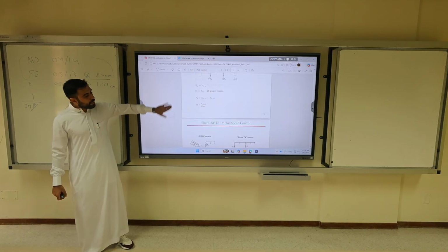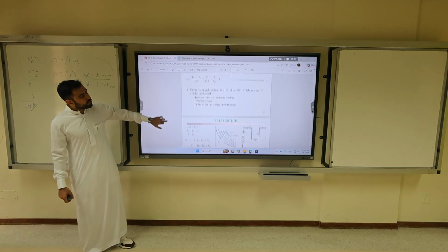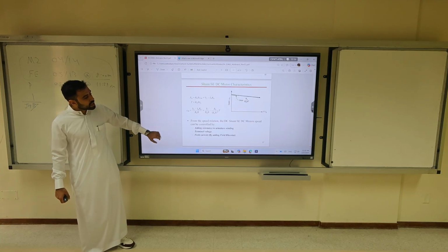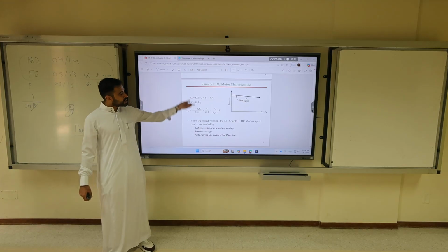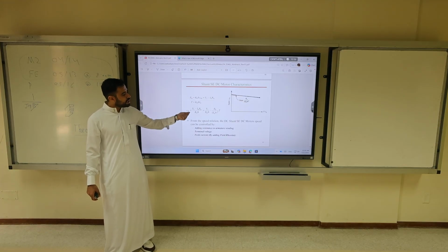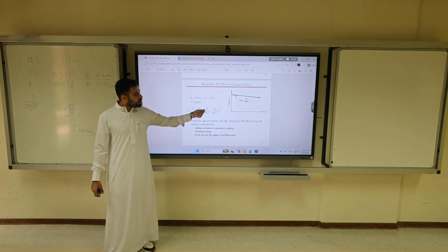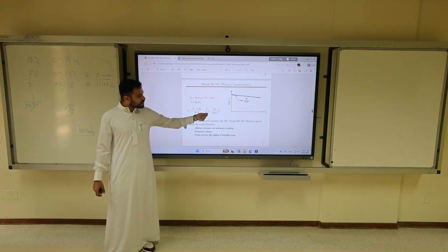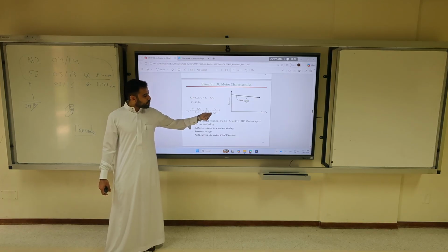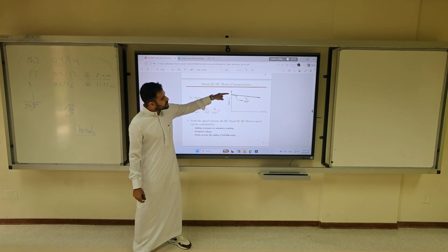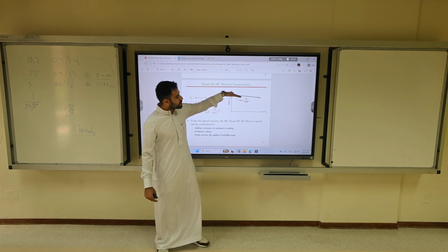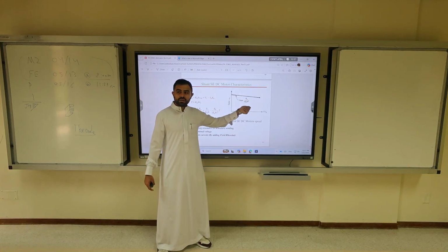Now, we talked about the power flow. We talked about the equivalent circuit. And what did we say here? We say this is from EE360. If you substitute the equation, the torque and E, omega is Vt over K flux minus Ra over (K flux) squared times T. So it is a straight line that has a slope of Ra over K times the flux squared.